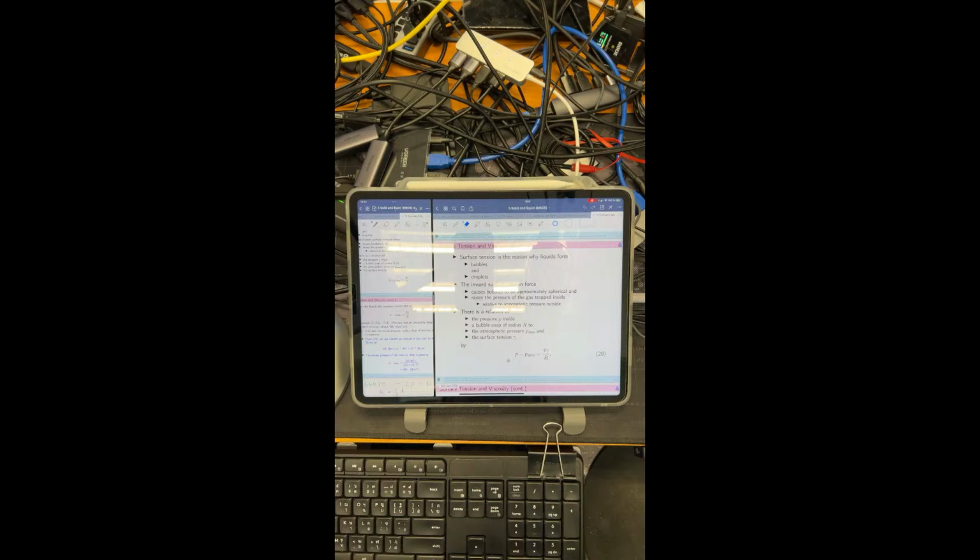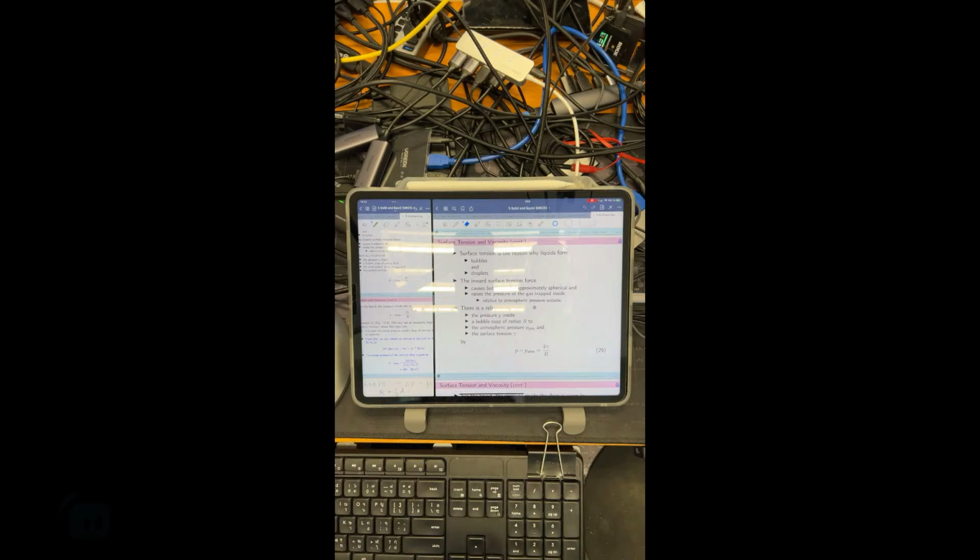Okay, let's continue our story. Before that, we arrived at this formula, the pressure difference: P inside minus P outside. Outside means the pressure at the surrounding, and inside means the pressure inside that fluid, whether in the bubble form or in the liquid drop form. The pressure difference in the bubble form is twice greater than the amount in the water drop, because of the surface tension. There are two formulas, for gamma and 2 gamma, and R is the radius of that bubble or drop. Let's say the drop is assumed to have a circular shape.